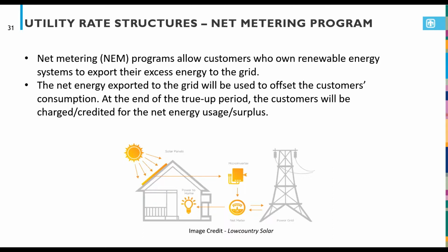Generally speaking, the longer true-up periods are more beneficial to the customers because the surplus energy in some months, instead of being sold to the utilities at wholesale price, can be used to offset the usage of some other months. However, that might not be true if the customer's surplus energy is paid at the real retail electricity price.